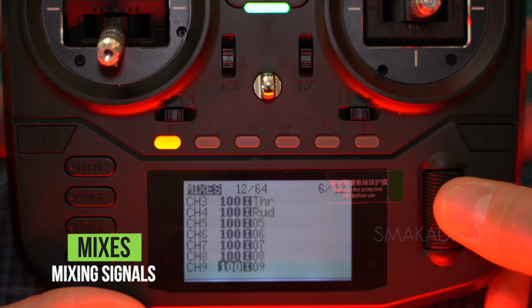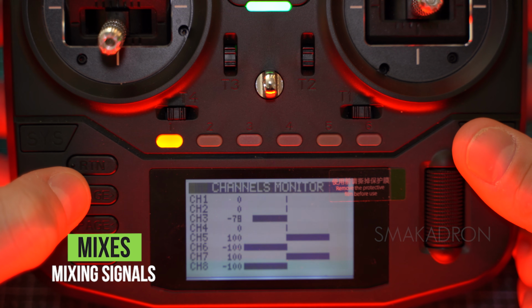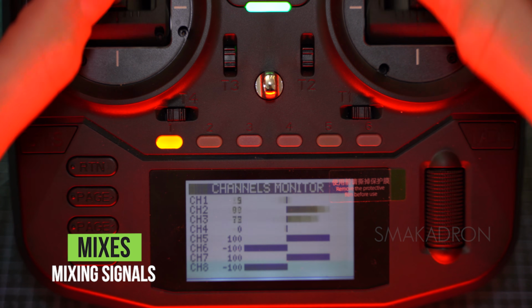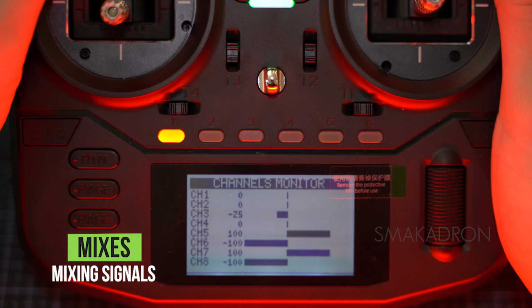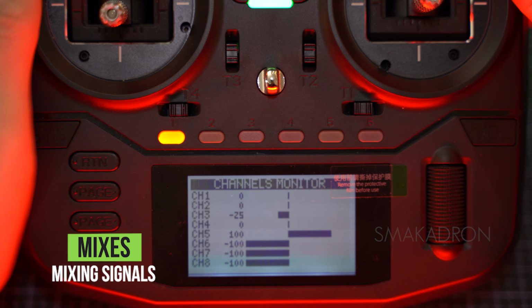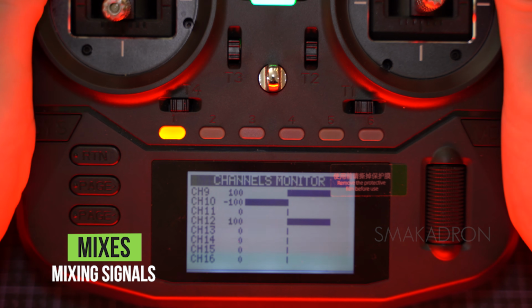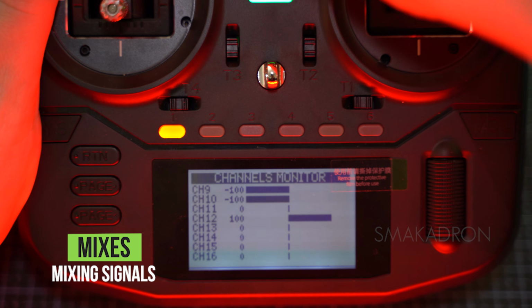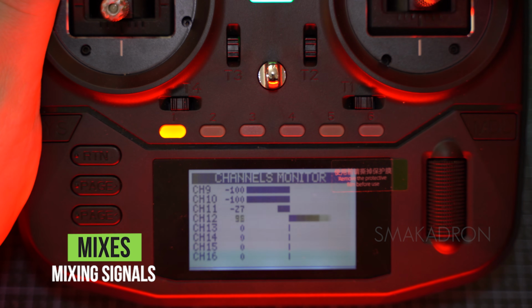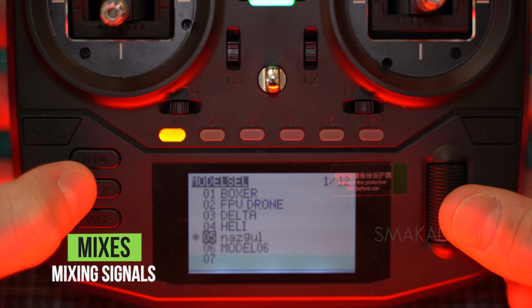We start by mapping our switch channels in the same order as on the previous inputs page. If you've already done it there, here you just need to go into the channel and it will automatically pull the selected switch or button from the previous inputs page. If you haven't done anything on the inputs page, then you start doing it manually in the same order. To check the result of the channel setup, go to the main screen and use the page key to navigate to the mixer's monitor page and verify that all channels are working correctly.